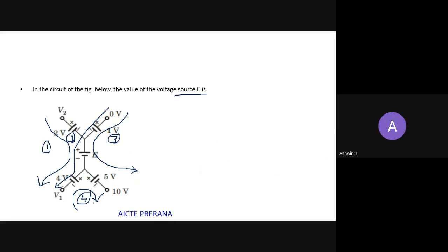You just see that? 3. Yeah, obviously, right? If I go for path 1, there are 2 unknowns, which are not given in the problem itself. And in path 2, there is one unknown, that is V1. It is not given. So we will consider path 3 and try to solve this. And you see this 10 volts, how it is connected, like this, right? Ground, this 10 volts is connected like this. So I'll always start from my known voltage source.